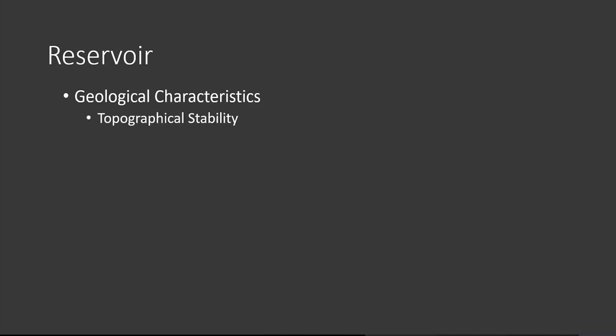So we are basically going into the aspect of what kind of geological characteristics are required for the reservoir. First one is the topographical characteristics. When we discussed the dams, we said that it is easy to construct a dam in a narrow valley, where the connection you need to make from one side of the valley to the other would be minimum. That would be the situation for the construction of a dam. But when you talk about the reservoir, it needs a large amount of area to store the water.